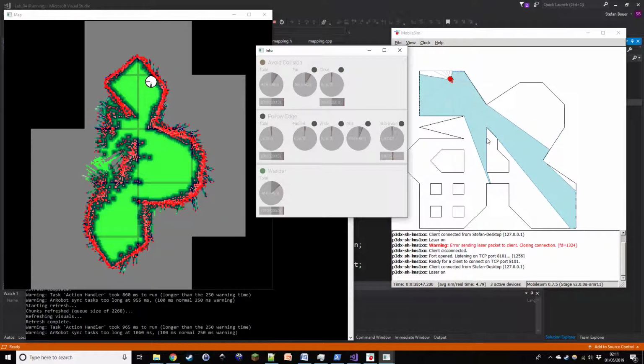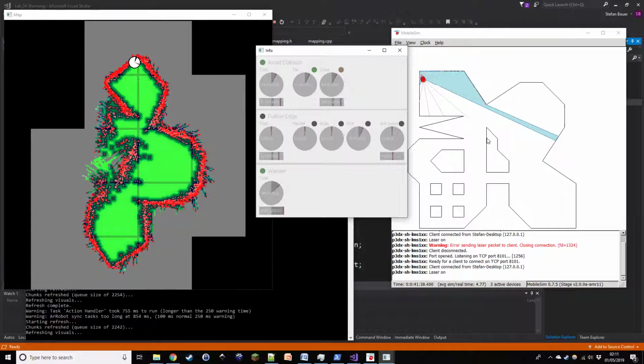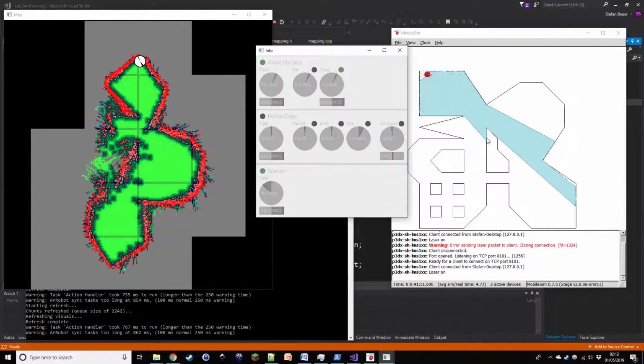In practice, there's kind of a lot of flaws with this approach. Some good things too, but quite a lot of flaws. I mean, fundamentally, I think the mapping solution is a good one. Obviously, if the map is infinite, it will take up infinite memory. But unlike a point-based approach, within a set map which the robot cannot escape, there is kind of a set maximum memory usage, which is good, because that avoids ending up in a thing where you can't run a simulation for an extended period of time without going into a memory overflow.